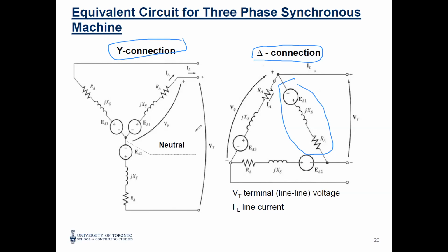And you can see here how we can connect them. Each one of them is like one of the circuits that you solve per phase. In the star or Y connection, we have something called the neutral that we can connect to the ground, for example, or we can add a reactor here just to limit the fault current, especially for asymmetrical kinds of faults.